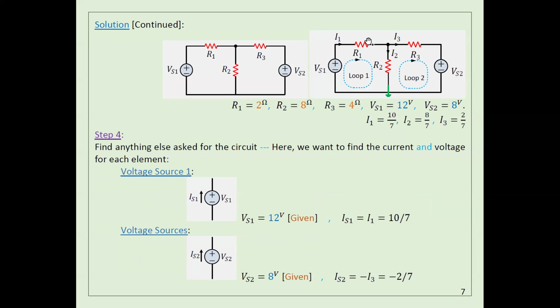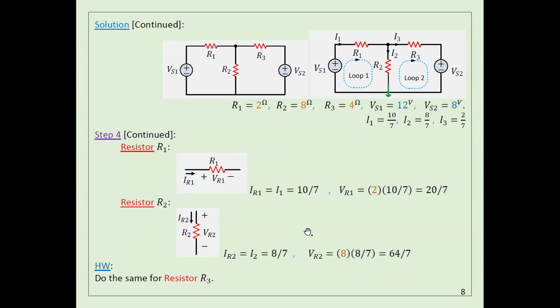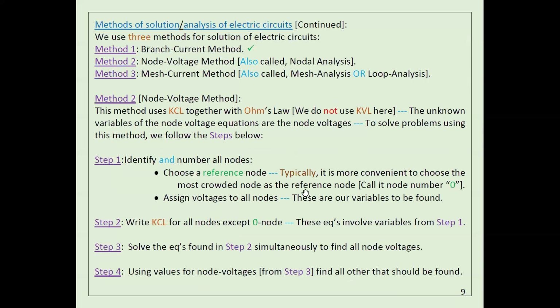And the current here is the same as the current here, because they are in series. Also, the current here will be the same as the current here. Usually the current goes from negative to positive for batteries, but actually the current here is going from positive to negative, so that's why you can see a negative sign here. But here it is going to be positive. Anyway, again, I just use Ohm's law, I multiply I by R. That's it. Any questions, guys?